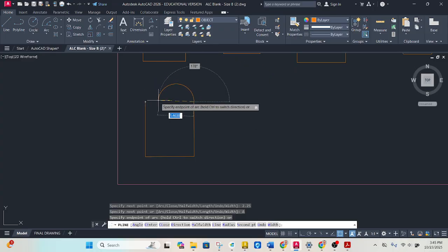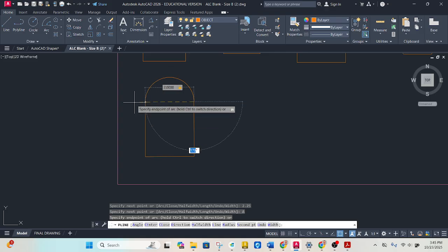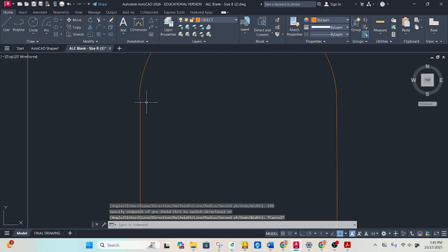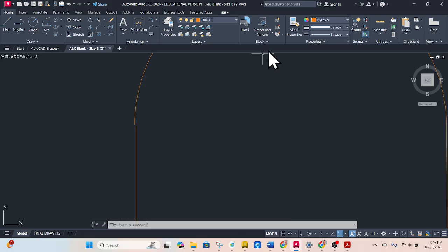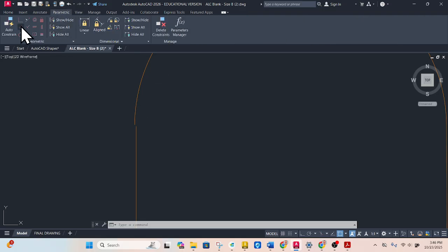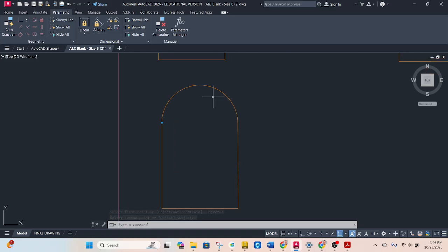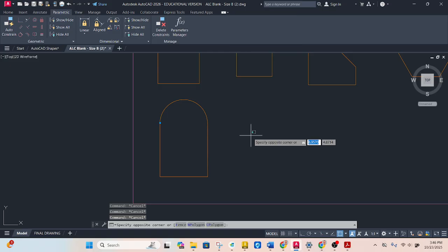I use it. So I want to type in 2, so it's the right distance, tab, and then 180. Enter. And then I can hit escape, and it's all done. But notice this is not quite touching there, so if yours isn't like mine, I'm going to use the parametric, and then tell this to connect right here, and that'll fit together again. I'm actually surprised that didn't just work, but anyway. So I've got that shape, and it's all good to go.